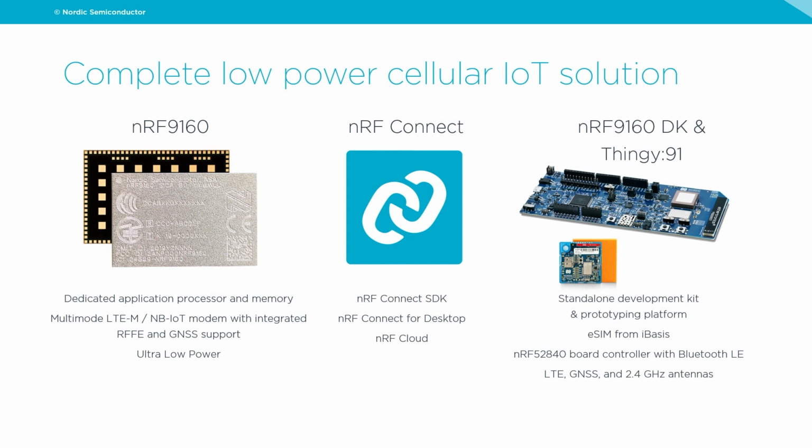In the middle, you can see we have the nRF Connect SDK, which is our SDK to be used with the nRF9160. We also have nRF Connect for Desktop, which provides a set of desktop applications which can be very useful. For example, the Programmer application is very good for modem updates.